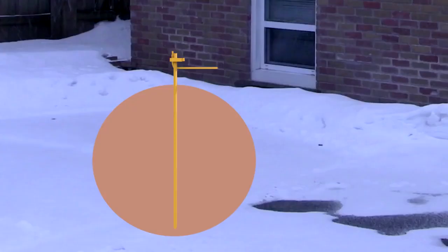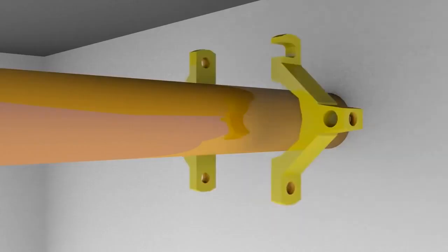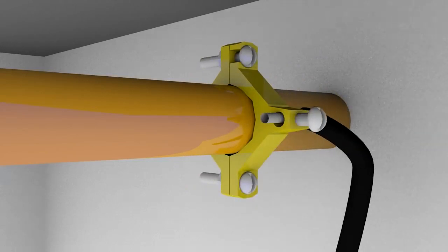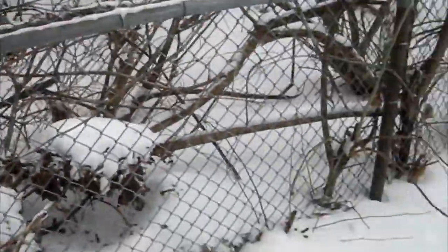A fairly safe way to ground that, if you don't have a ground rod that you can connect to directly, is to find a metal pipe that you're certain goes into the ground. Like this copper cold water intake pipe from the city. Or this metal fence would do, since it makes plenty of contact with the ground.